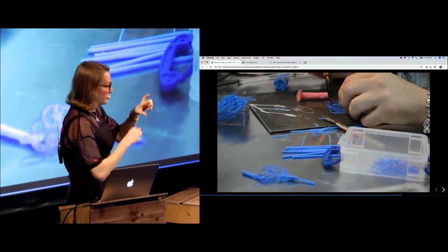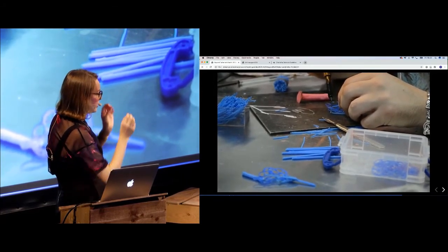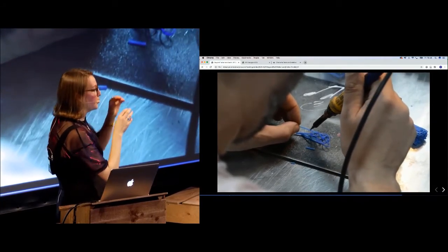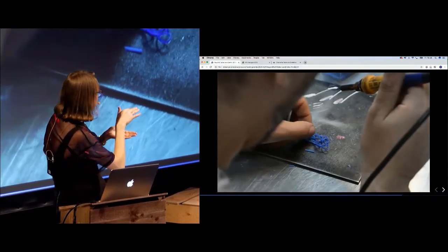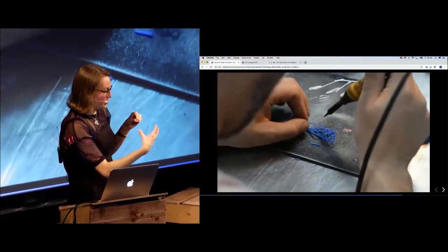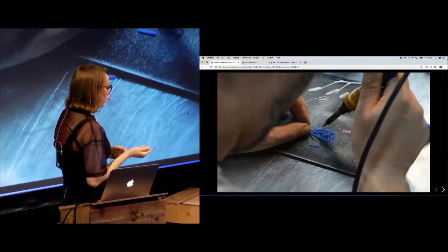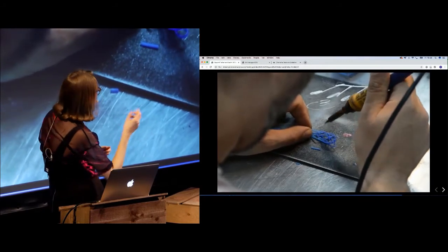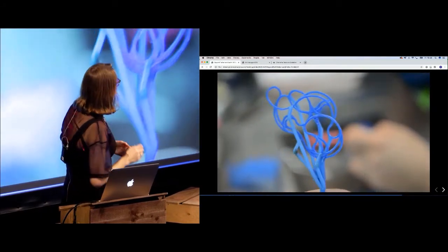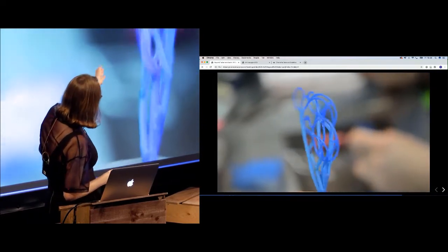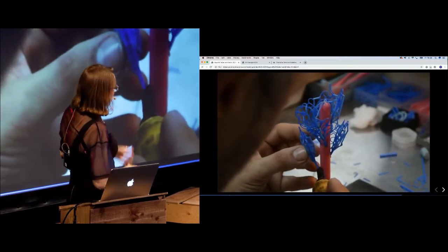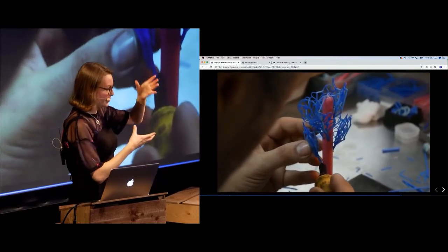But for the metal to get to the end of the thing, it needs to have space to run down, otherwise it will cool before it gets to the end. So you need to make these things called sprues, which allow the metal to get to the end of the piece. It turns it into a bit of a tree structure. But yes, it used to be extremely manual, and now I'm so glad that I wrote the algorithms to 3D print it. So it gets this, and then you put them all on this root sprue. So you have a whole wand of these wax things.